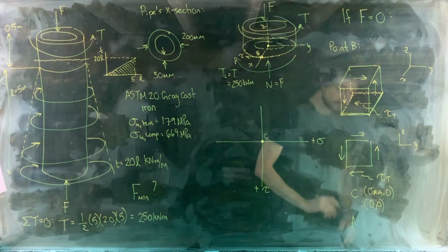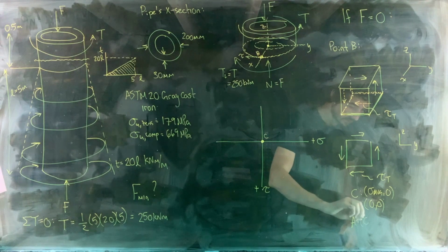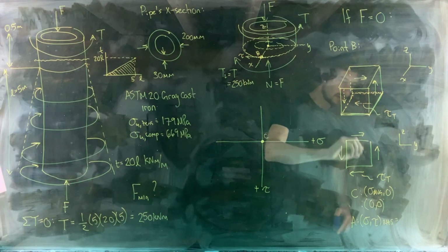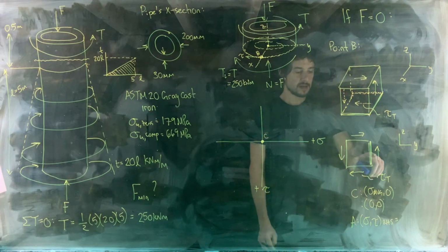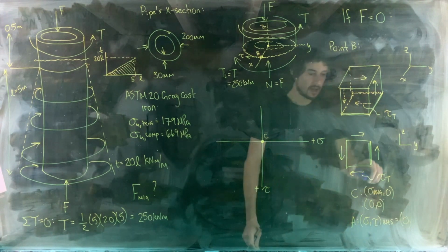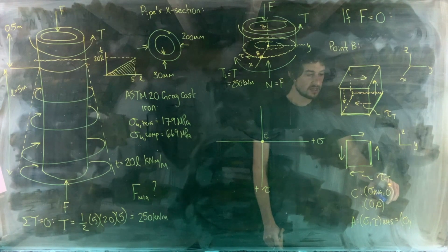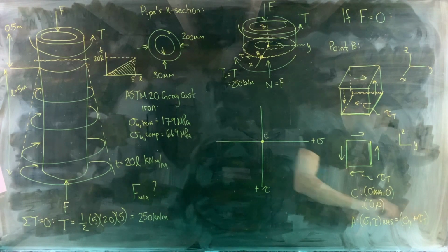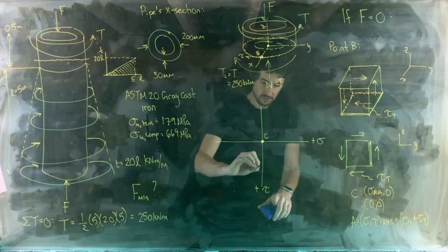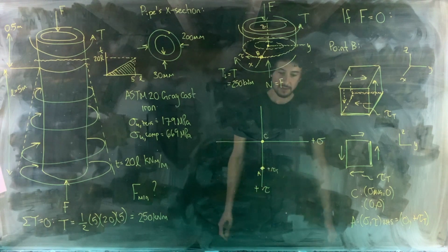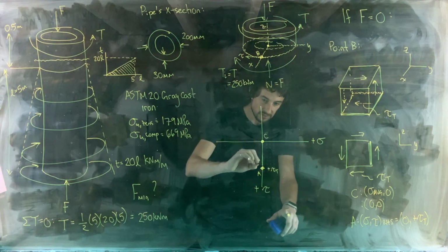Point A, our reference point on the circumference of our circle, is given by the stresses on the element's right-hand side. There's the right-hand side. So we've got no normal stress and a shear stress tau T that is upwards on the right-hand side, so it's positive. Down here, here's point A, located at positive tau subscript T, and the radius extends from C to A.